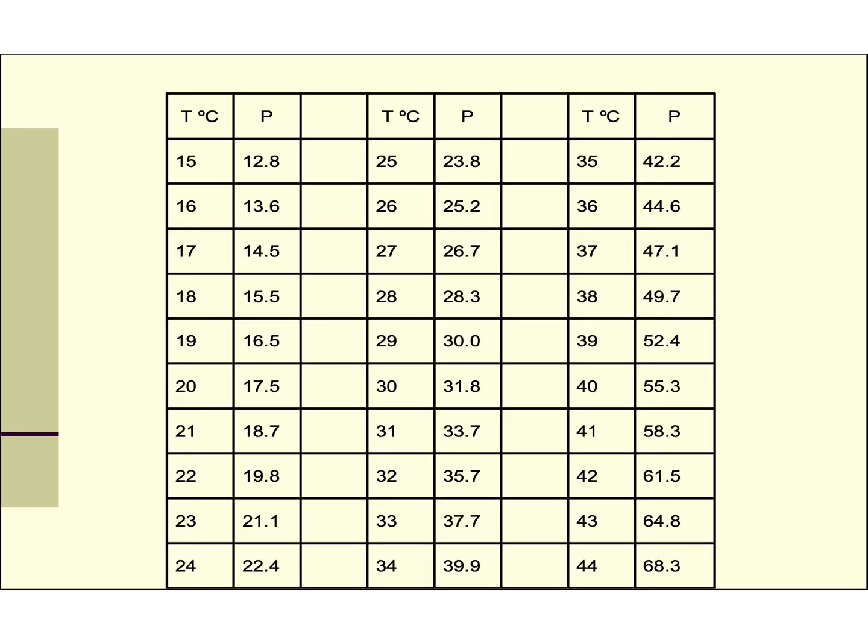Here's a chart showing vapor pressures, or saturation pressures, of water vapor at various temperatures. Keep in mind these are fully saturated pressures, so the actual partial pressure is this number multiplied by the relative humidity. So for example, at 29 degrees C, the vapor pressure, or saturation pressure, is 30 millimeters of mercury. If we had 70% relative humidity, we'd take 0.7 times 30, or 21 millimeters of mercury, would be the partial pressure of water vapor we would use in our equation.